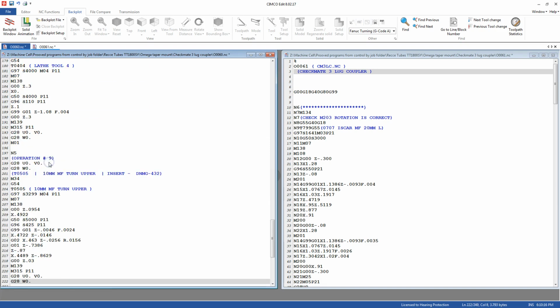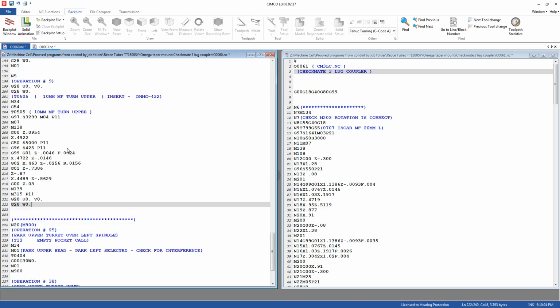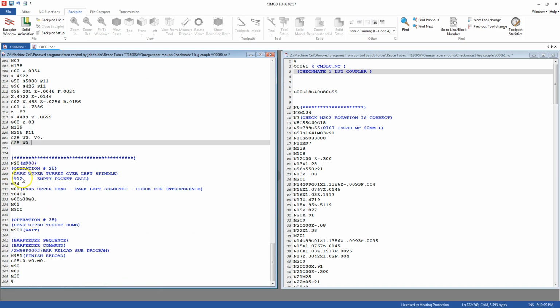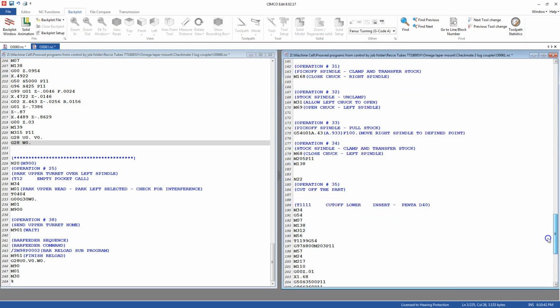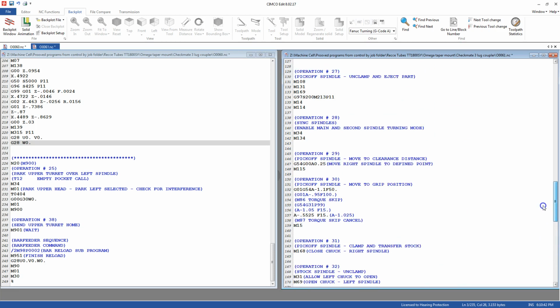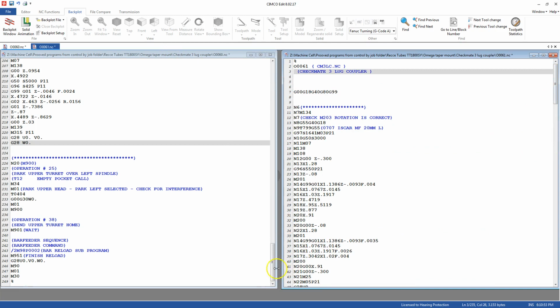So it's not uncommon for machines to have a personality, especially these multi-axis twin spindle machines. And so what you're going to find is that you're going to develop some sequence of parking the turret that works in the control and actually runs. And then after you spend a lot of time on that, you're going to use a program as a shell such as this to make it work. And that'll be one of the only ways that you can actually reliably obtain a working program.